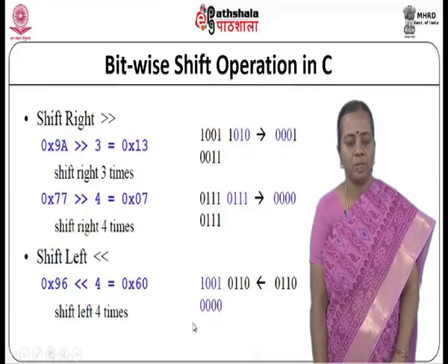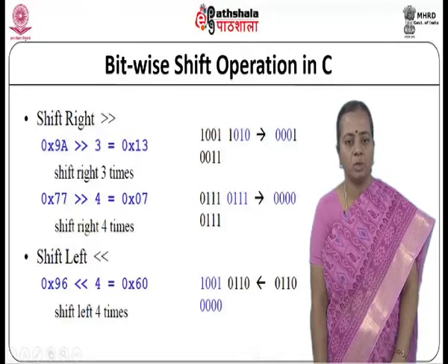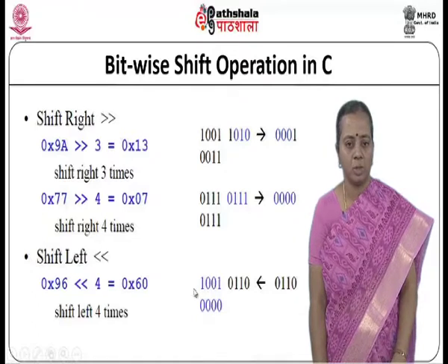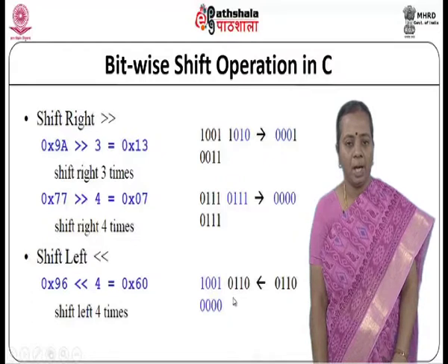So, when I am shifting it left, you just see that this 0 1 1 0 comes to this position and 0 0 comes to this particular position. Just see that this is nothing but 6 and this 0 is coming over there, all 4 zeros have to come over here. So the whole thing is getting shifted by 4 positions, so that this goes completely and this particular nibble comes over here and the right side nibble will be 0 0 0.